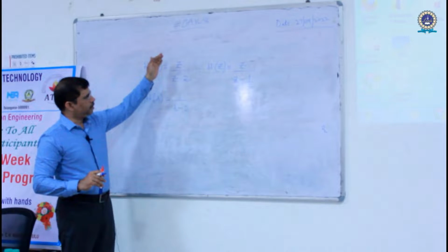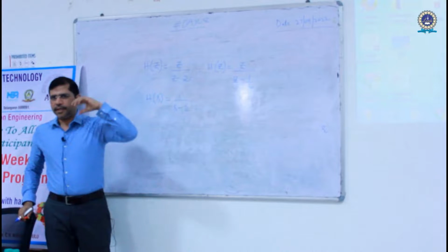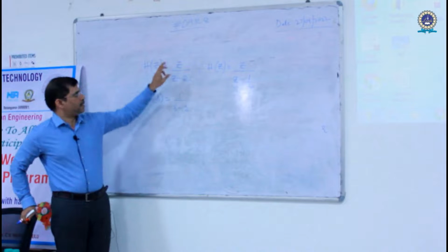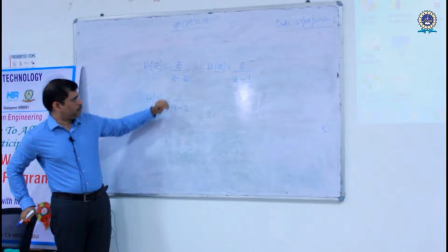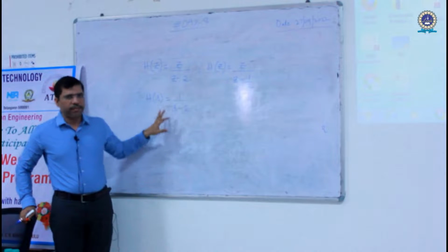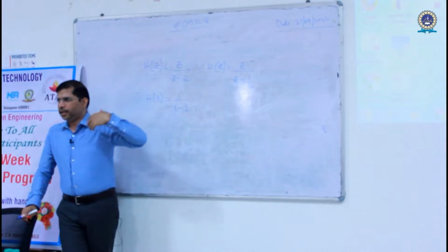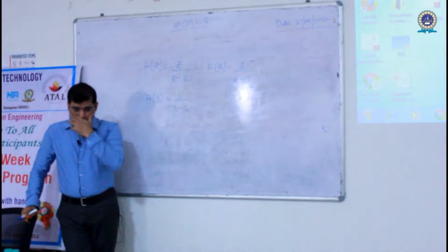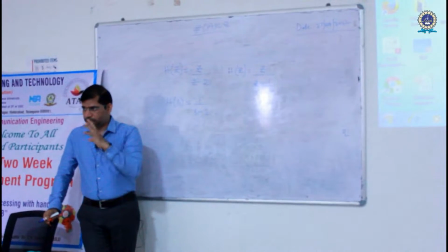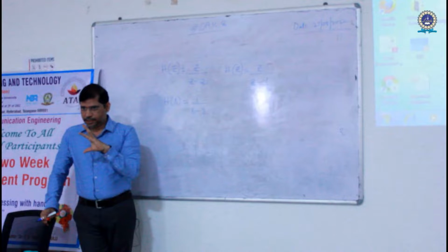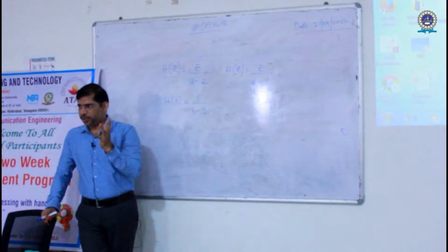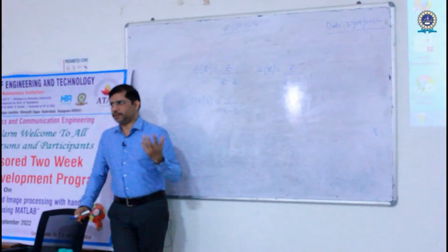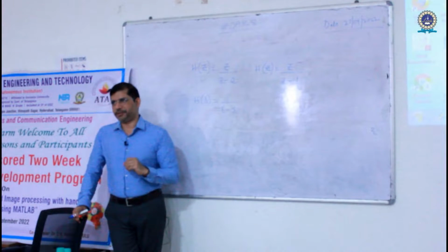Why you have Z in the numerator, once we understand the linear phase concepts, then probably you will understand here. Z by Z minus 2, and the standard approach here is 1 by S minus 2. It cannot be S by S minus 2. Okay, so there is some kind of misinterpretation between analog and digital, that you can replace S with Z, but normally that's not correct. You cannot replace S with Z because there are some kind of transformation techniques that we need to follow.